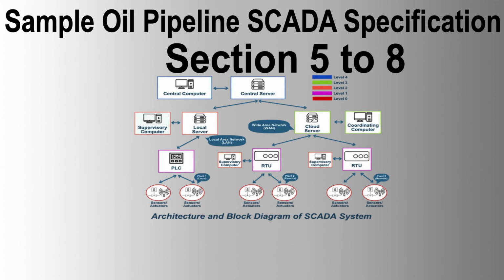Analog data treated as discrete snapshot samples, averaged and compressed over time. Discrete status data treated as timestamps on state changes. Sampling averaging intervals for real-time data processing into historical data are user-definable and configurable. System provides 1-minute averages for 7 days, 10-minute averages for 31 days, hourly averages for 1 year, daily averages for 5 years, daily maximum and minimum values for 1 year.